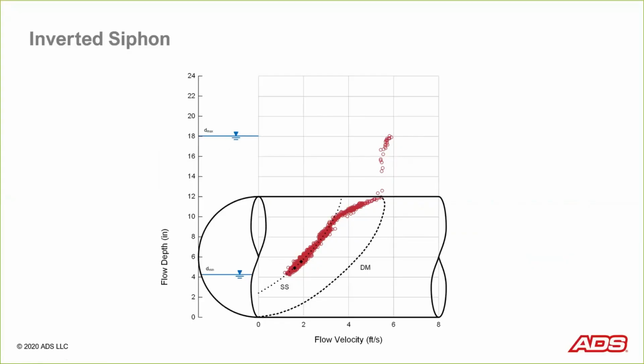So I went back to this municipality and I said I need to get the design or as-built slope of this particular line. I'm estimating a roughness. I used the design method to draw a curve on this pipe, a Manning equation. You can see that curve is plotted here, and the only place it agrees with the data is at full pipe. I've also taken the Manning equation and used the siphons method to plot this curve right here. And you'll see it fits most of the data until I get up to about 10 inches or so.